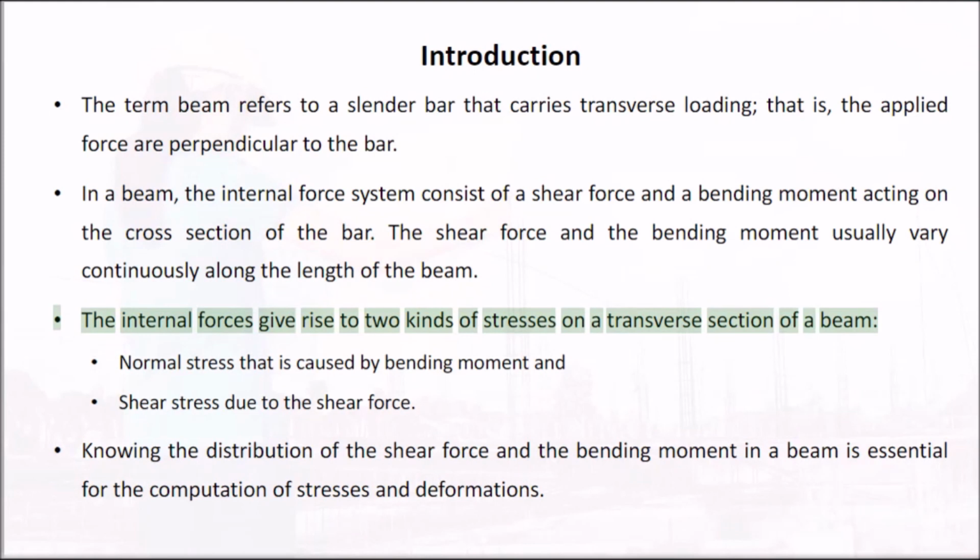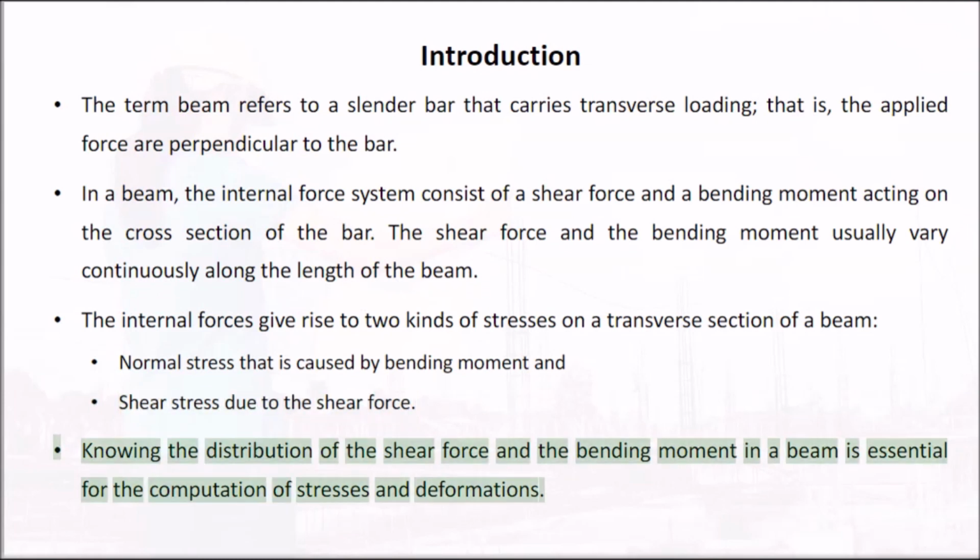The internal forces give rise to two kinds of stresses on a transverse section of a beam: normal stress that is caused by bending moment, and shear stress due to the shear force. Knowing the distribution of the shear force and the bending moment in a beam is essential for the computation of stresses and deformations.